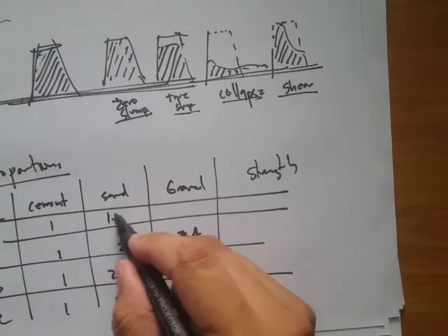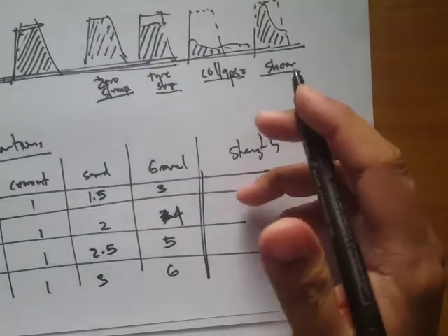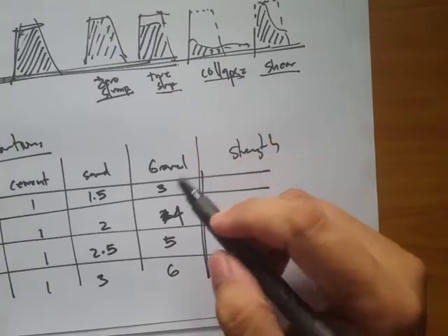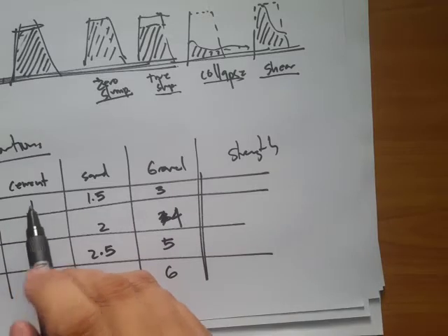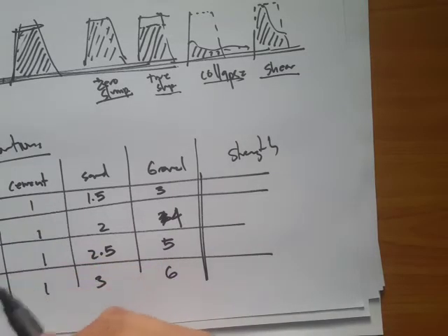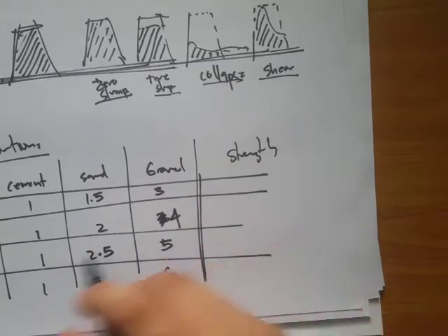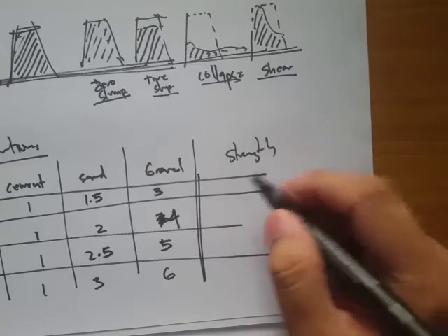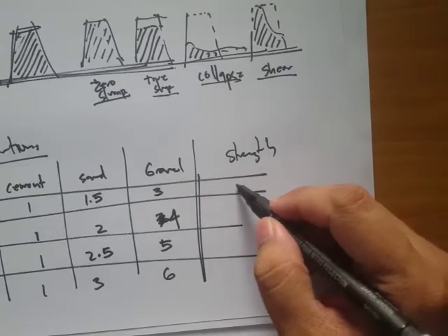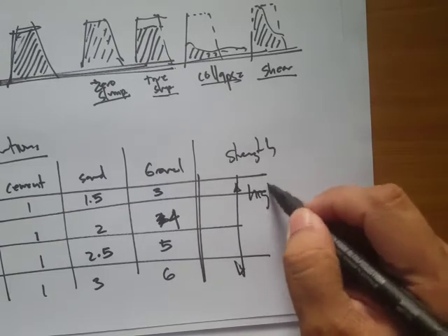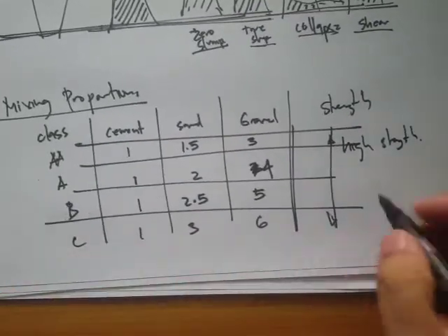And there's also data on class double A. We have 1:1.5:3. So you notice that for a given volume, there's more percentage of cement, meaning more cement in that given mix. If you get more cement, then there's going to be high strength, and sorry, the bottom would be low strength.